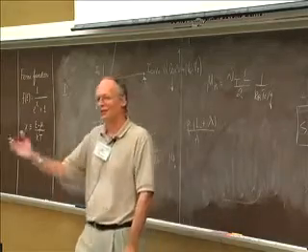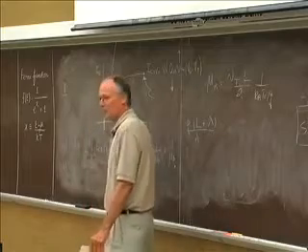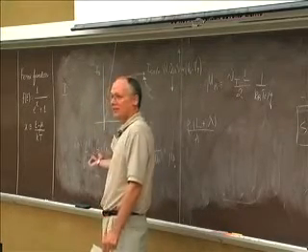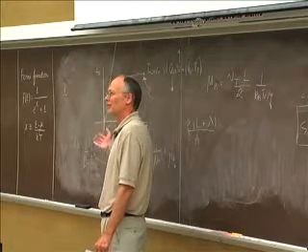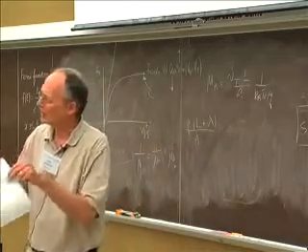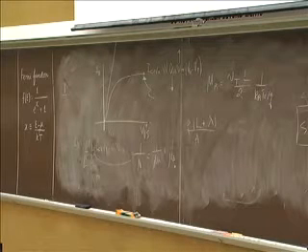These guys are always doing clever things. There's been a lot done in recent years on strain engineering, by straining silicon effectively to lighten the effective mass and get a lot of these benefits, which makes it even harder for anything to compete against silicon. But as I said, you work the numbers, it looks like there's an advantage there, but it's got to be done in a well-designed device.